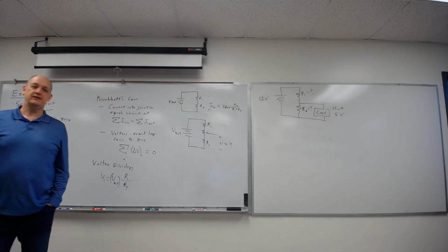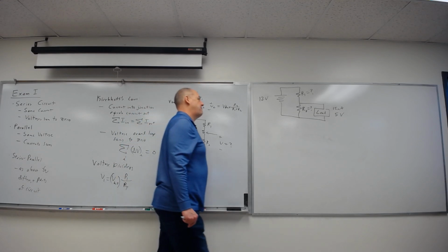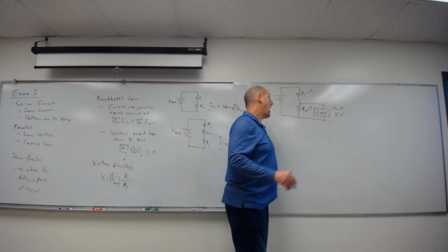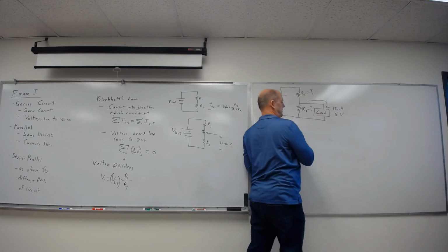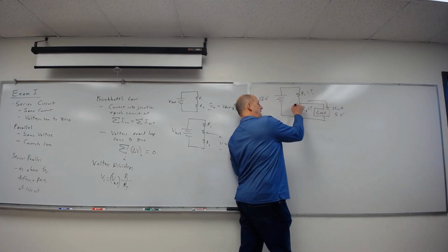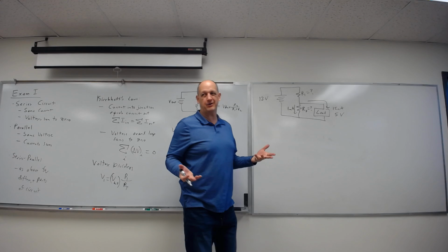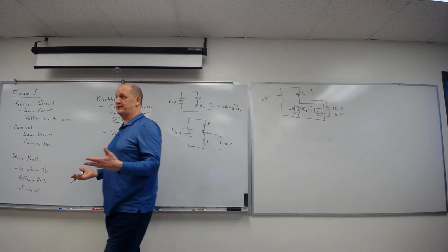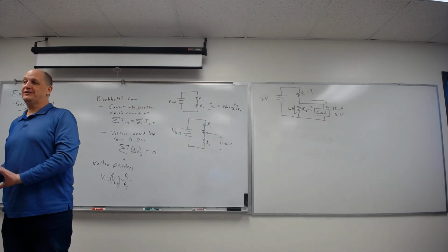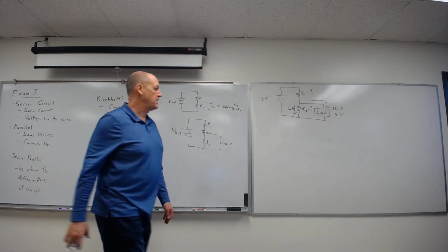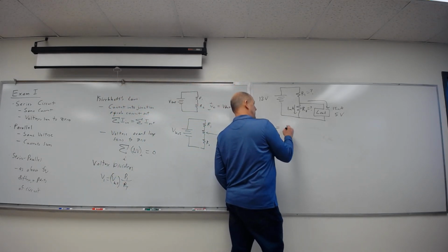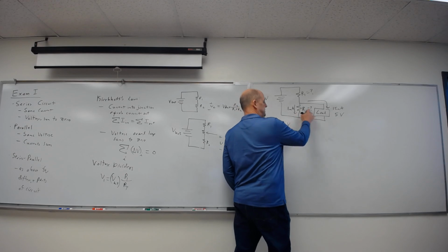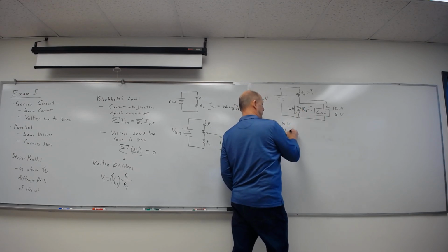5 kilo. Yeah. So here's what I'm going to do. I'm not going to pick resistors first. I'm going to come over and say, I need 15 milliamps to run over here, right? 15 milliamps. I'm going to just pick 1 milliamp. That's kind of a standard thing to pick for this. I need some current going through it to create a voltage. So let's pick a small current, at least relative to that other one. So if I do that, R2 is going to be 5 volts, because it's parallel with that, over 1 milliamp.